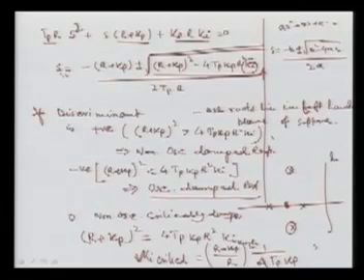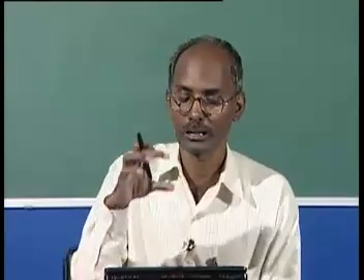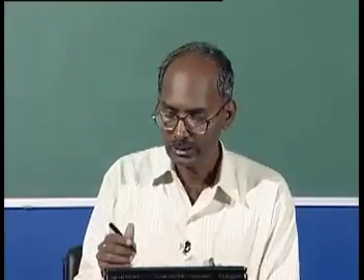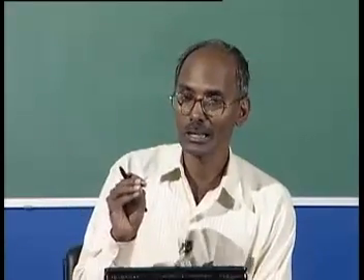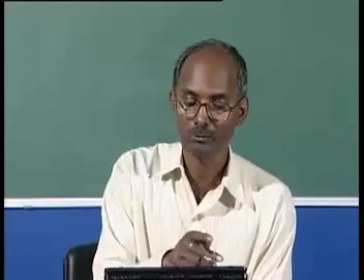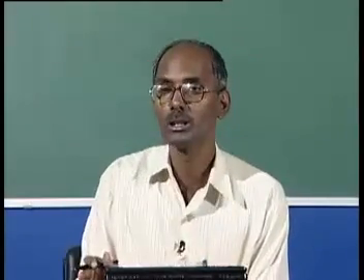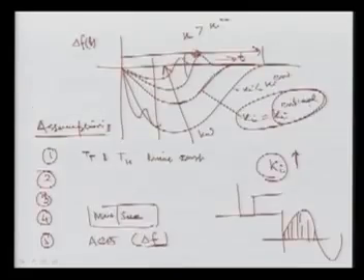By setting this gain value we can get different performances, in terms of settling time and differences in overshoot, and this Ki we calculated. But in all the cases we found that if we use the integral controller, the reset control, it reduces our frequency error. At the same time, from this equation and this graph we can see it is a stable closed-loop control, and we made various assumptions and justified them.